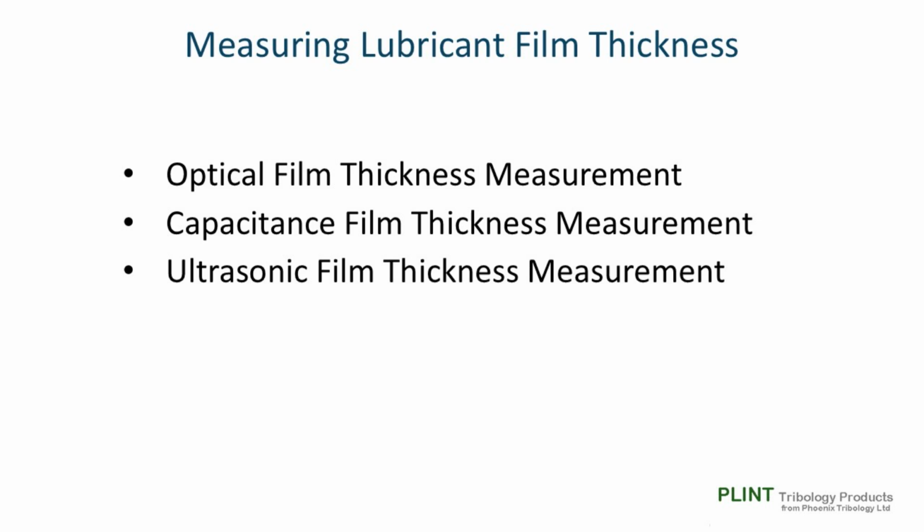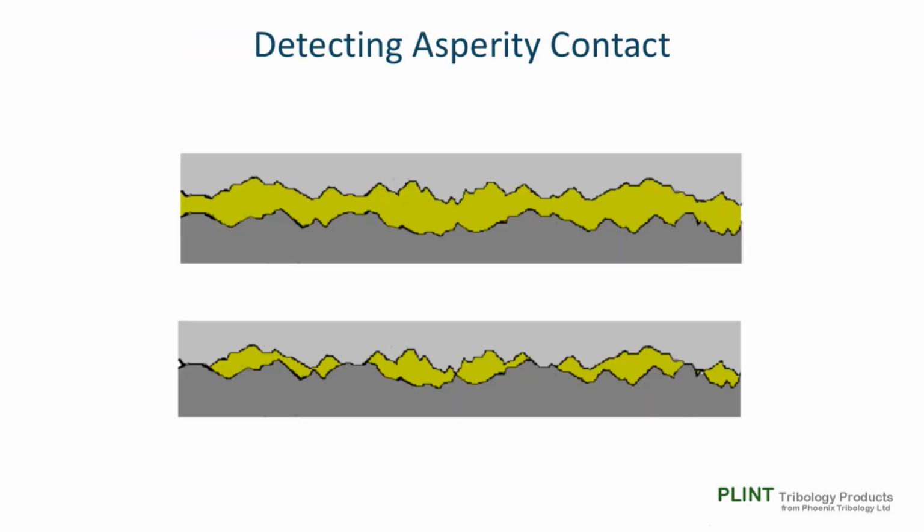Although this is a viable measurement technique for systems in which a steady-state lubricant film occurs, for example a plain journal bearing, we have some doubts with regard to how practical such measurements are when measuring transient film thicknesses, as must occur when a rolling element passes a point adjacent to the sensor.